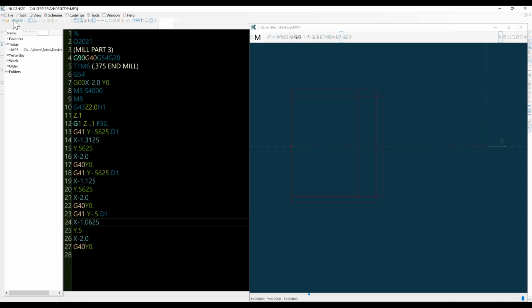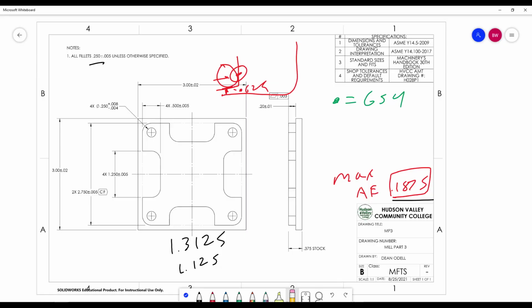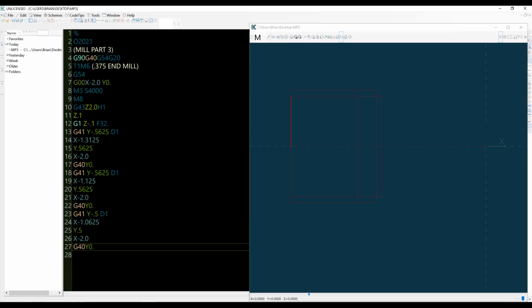That takes care of our initial roughings of all 4 of these pockets, essentially, because what we're going to do is just invert them over. So I'll show you the first one, and then you could do the remaining 2. I'll catch up quickly just to make this video as short as possible. We'll need to invert some x and y's. So let's move clockwise. Looking at discriminator, G40 is done, this pocket's done.